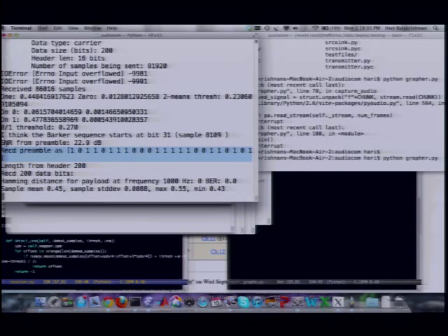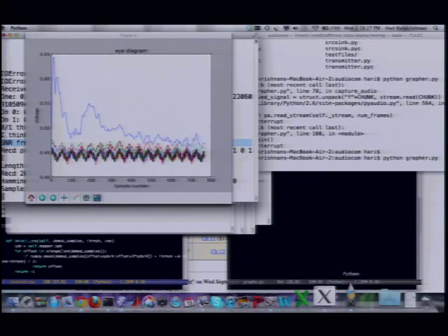We also plot out the signal-to-noise ratio of the transmission, and that shows up there. If that signal-to-noise ratio is something like 20 dB or 15 dB, things are fine. This system doesn't really work below 15 or 10 decibels. It means that the signal-to-noise ratio is too low, which means you either have to yank up the volume, or you have to go to a quieter location, or, and I'll explain this, you have to change some of the parameters in the program.